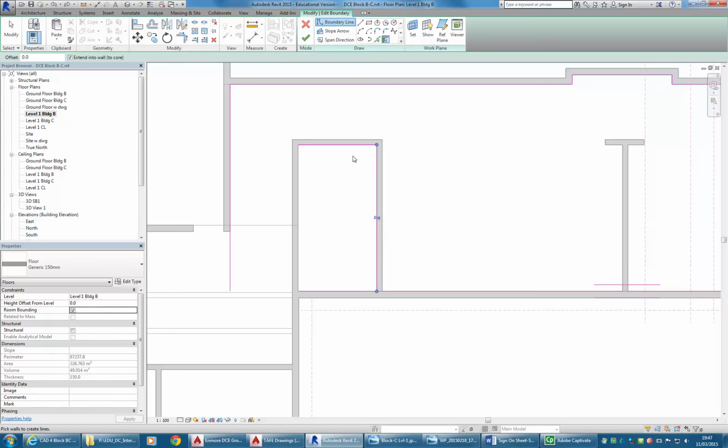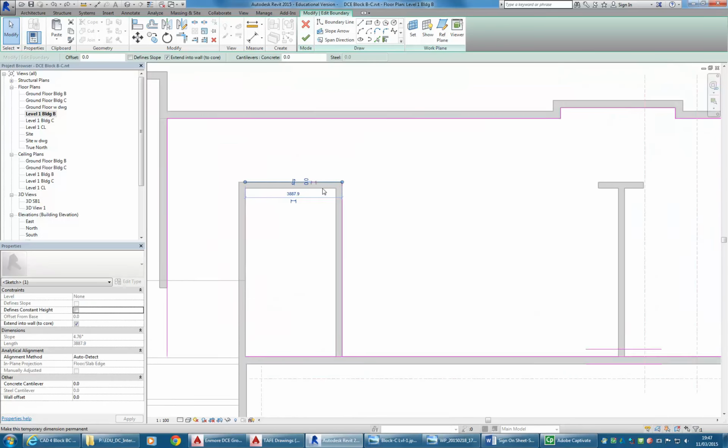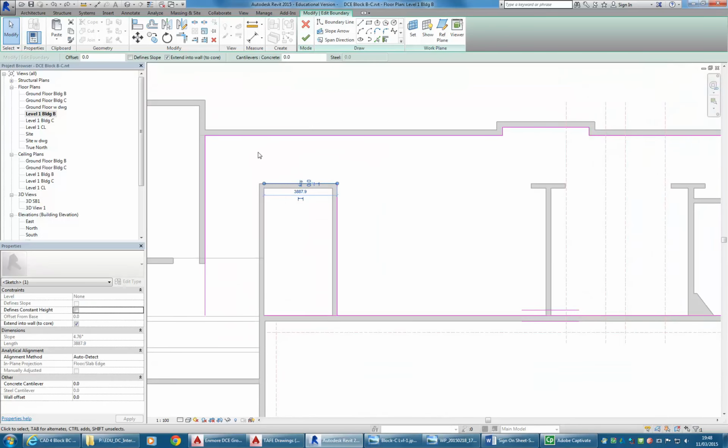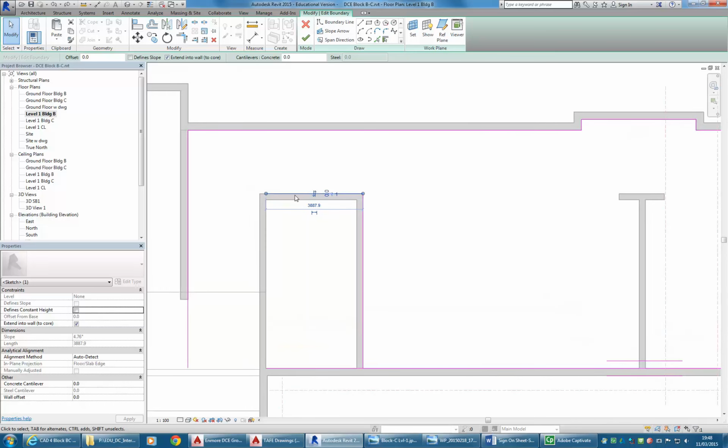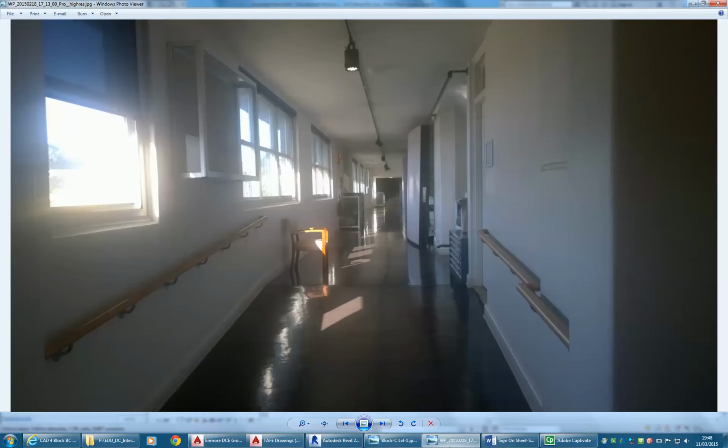Again, when I try to flip it, it's going to move this one, so, well, do we actually need... Yeah, it's a bit of a funny one. If you think about what's happening with that floor there, it's really going inside this room at the higher level. Oh yeah, so they've been a bit naughty. That's not legal anymore. You can't do that anymore in Australia. BCA says no, coming out of an angle. You can't have an inconsistent riser height, even in the threshold. I'm fairly certain of that.